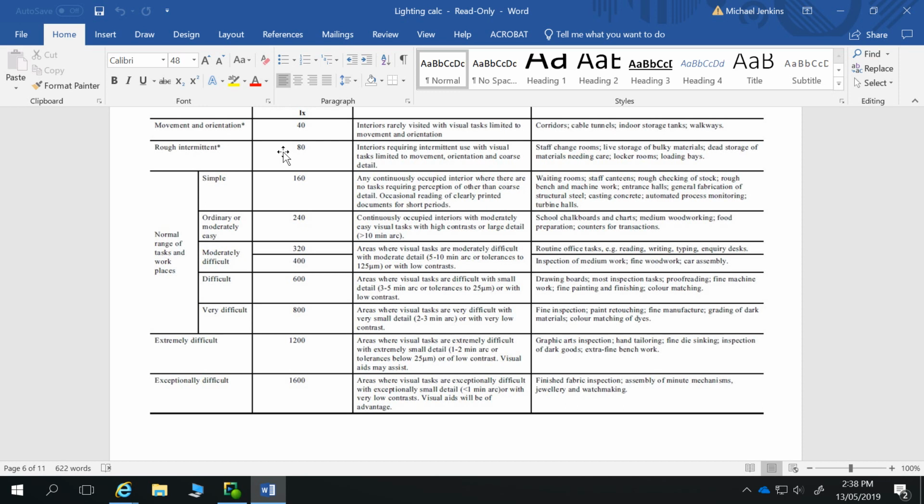That one is going to be quite simple because it's probably going to be a single globe, unless you're having divided stalls, then you have to have a light source in each one of those. But it's probably going to be a single globe for those rooms, and something of around 1,000 lumens to do that. So it'll be quite simple.